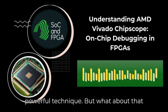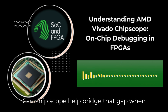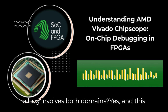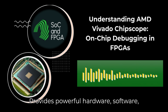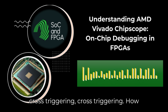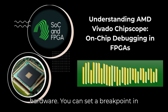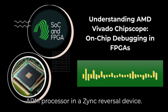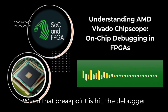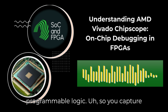It's a powerful technique. But what about that hardware-software boundary problem in SoCs? Can Chipscope help bridge that gap when a bug involves both domains? Yes, and this is another critical capability. Vivado provides powerful hardware-software cross-triggering. Cross-triggering, how does that work? Two ways. First, output triggering, which is software triggering hardware. You can set a breakpoint in your software code running on, say, an ARM processor in a Zynq or Versal device. When that breakpoint is hit, the debugger can automatically send a trigger signal out to the ILA running in the programmable logic.